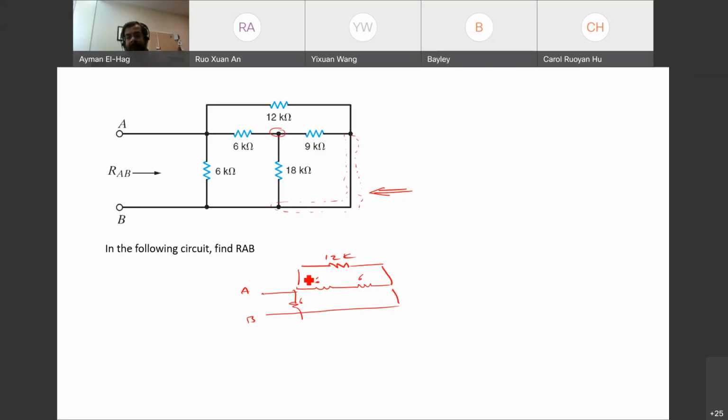Okay. So now it's very clear to me that, okay, now the 6 and the 6, they are in series. This 12 with this 12, they are in parallel, and then everything is in parallel with the 6. So it's very important, and this is what I strongly suggest to the students who are working with a resistance question: please draw each step so that you can visualize it. Okay. Now, how did I come up with this? Now, let's see. These two are in parallel, okay, and there is 6. Now, how to figure out that this is how it looks like?